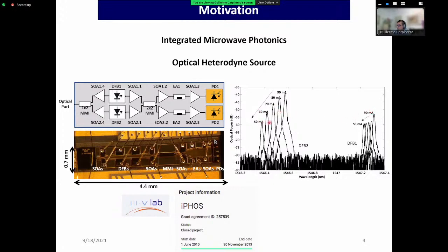These are combined in this laser, but the thermal effect also affects the other laser, which is just lying next to it. This made it difficult to reach some frequencies, and of course the tuning is a bit complicated with this effect. We were able to tune from 5 to 100 gigahertz, but we had to know our lasers before we could achieve a given frequency.